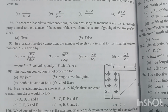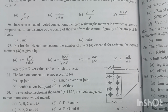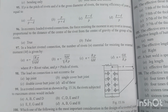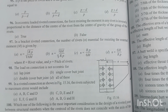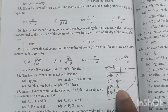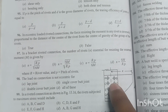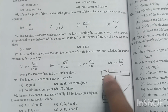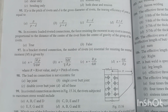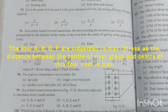Question number 98. The load on connection is not eccentric for double cover bar joint. Option C is the right answer. Question number 99. In a riveted connection as shown in figure 15.16, the rivets subjected to maximum stress would include A, B, G, H, because the distance between the rivet group center and the rivet will be maximum for these four rivets. Okay, so these four rivets will be subjected to maximum stress.